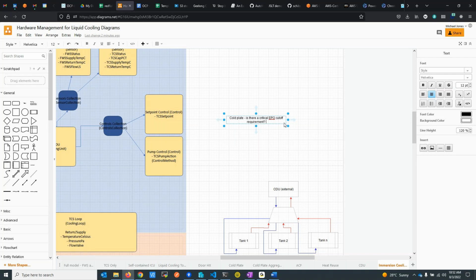I don't think we need to cover the existing air cooled critical failures. Well, what I'm saying is, if there is such a control in the air cooling, then yes, we definitely need to consider that when we talk about direct on chip cooling or chassis level immersion. If there is no such control, then we need to understand why with tank immersion there is a requirement to shut down the PDU, because as far as I know the server will regulate itself, it will shut down itself if the temperature goes up.